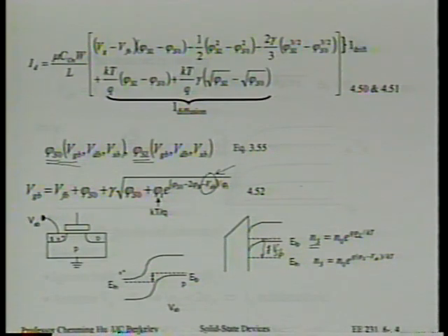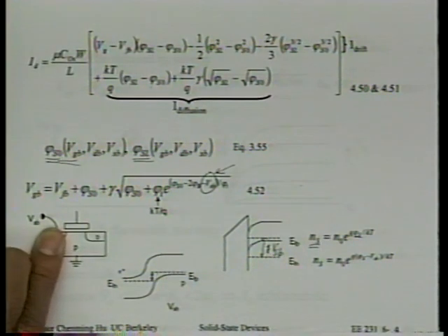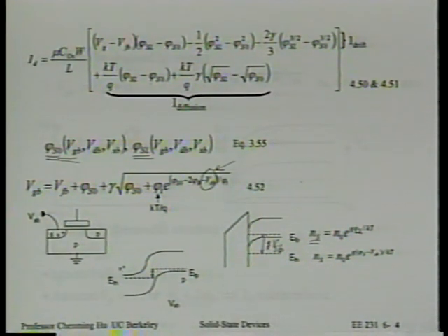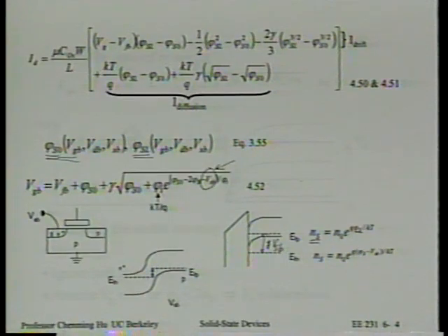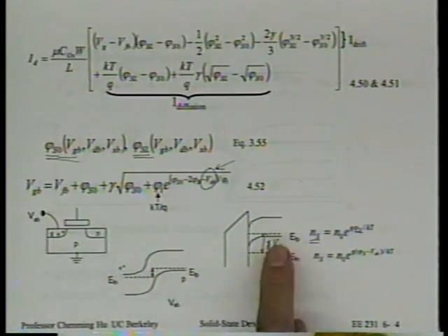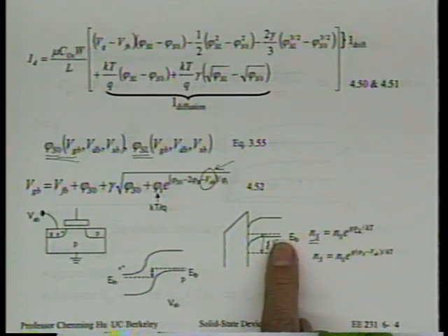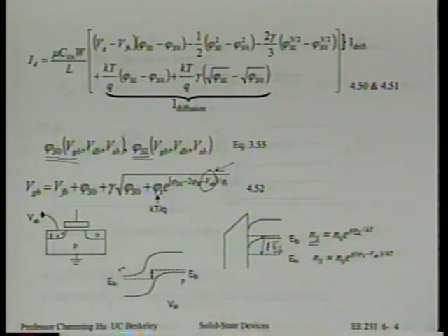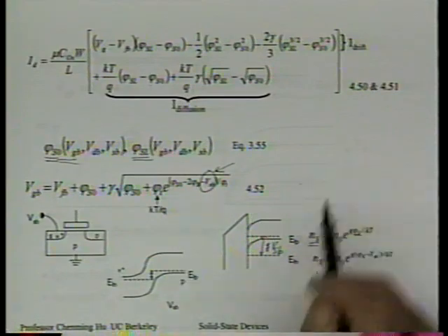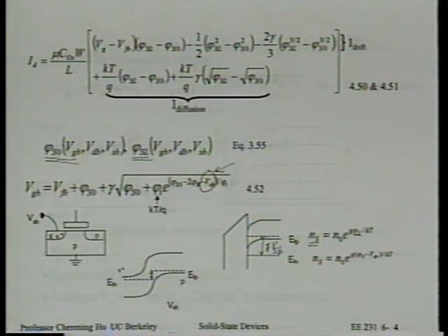In fact, we have heard in chapter 3 that the electron inversion layer is very weakly coupled with the holes in the body. It takes many minutes for them to reach equilibrium. That's how long thermal equilibrium takes to be reached if we did not have the source, remember? It takes minutes for the inversion layer to be established, right? That just shows you how weakly the inversion charge is coupled to the holes or to the EFP. On the other hand, it's very strongly coupled to the source, because that's where the electrons come from. You follow what I'm saying?